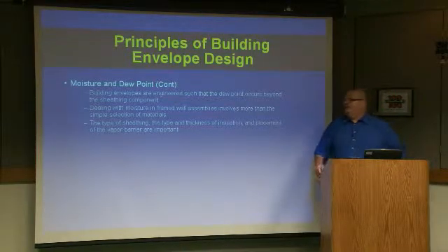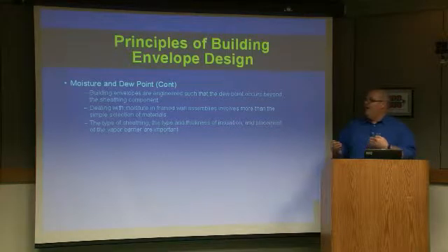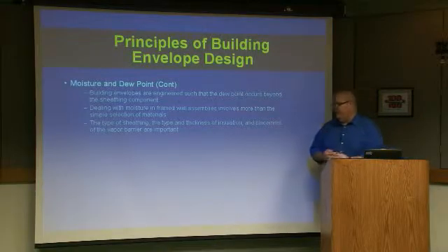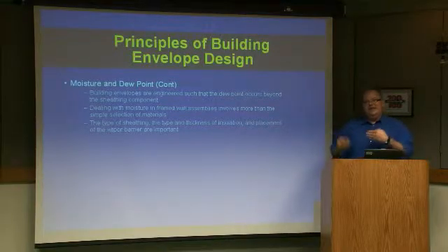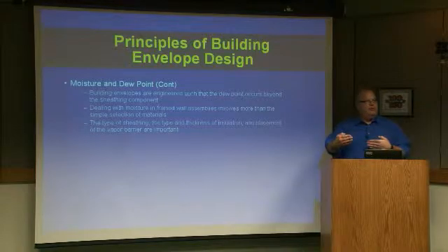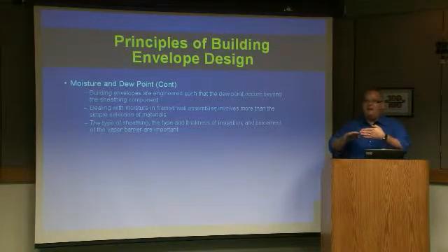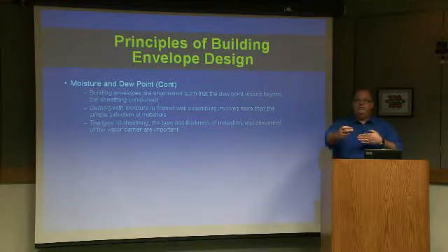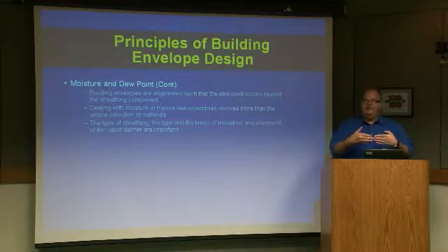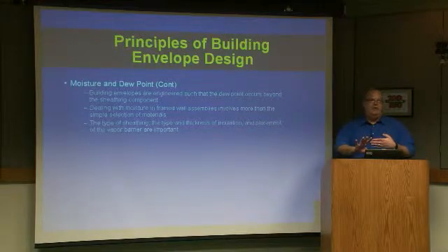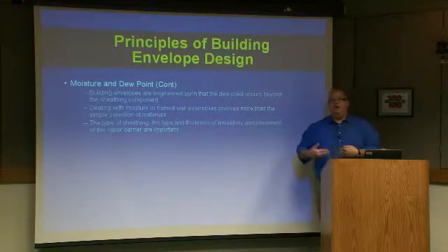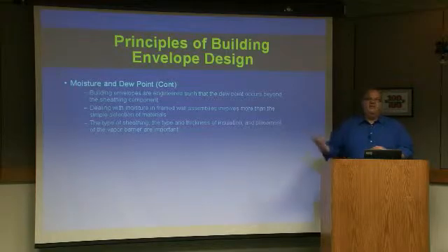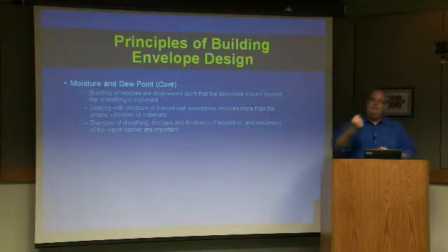Now the reason they do this is to get all that insulation value out in the cold, wet part of the building. When you do that, because the extruded polystyrene is a vapor barrier, the inside and the outside both work for you. In the wintertime, water vapor can't drive from the warm interior environment out into the cold insulation because it can't get past the interior face of the insulation. It's a vapor barrier. So you don't get that moisture buildup out in that foam. In the summertime, when that red brick wall is storing tons of moisture and the sun comes out, the air conditioning can't pull it into the building because it can't pull it through that foam board. It's a very successful model.